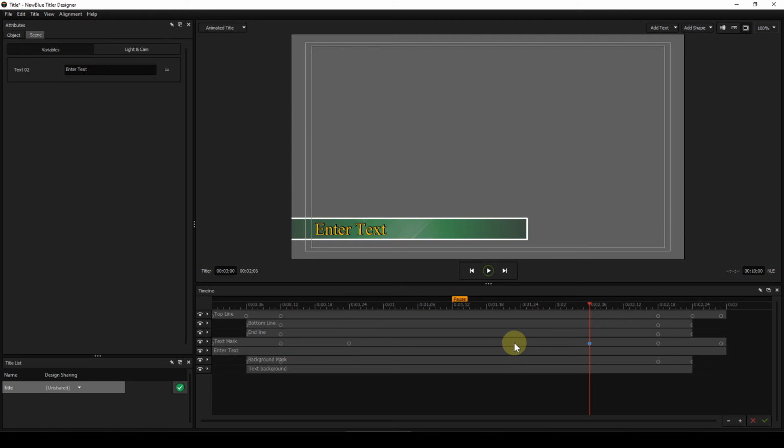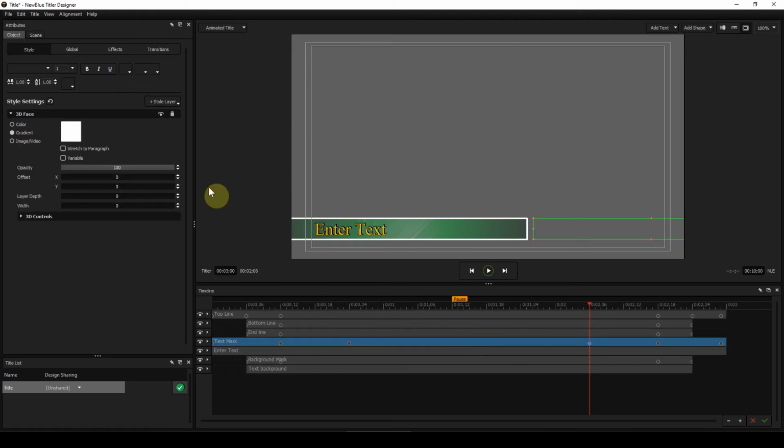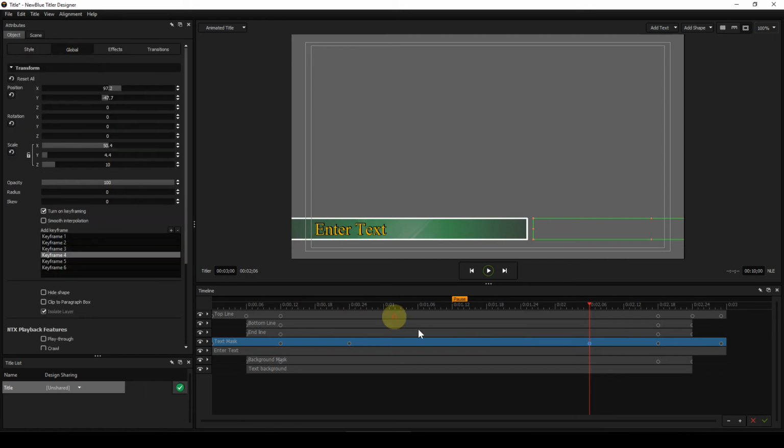To generate that keyframe, I would go to the Global tab, highlight the element, click on the keyframe that I needed to replicate, right click and select copy, then move the cursor, the playhead, to the place where I want the keyframe to be, and then click the plus button here, which adds the keyframe.